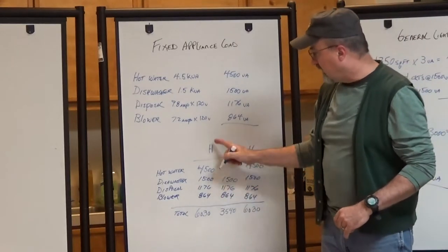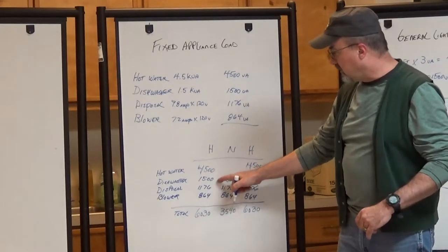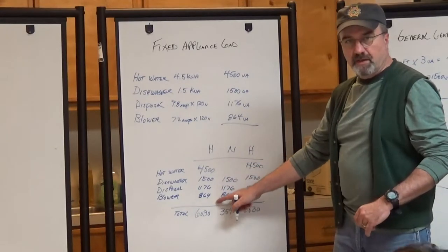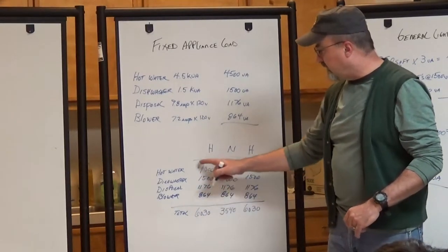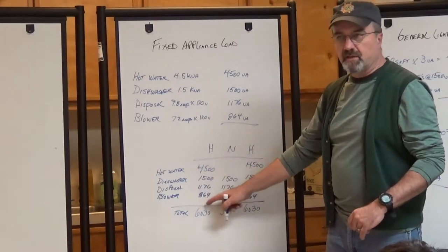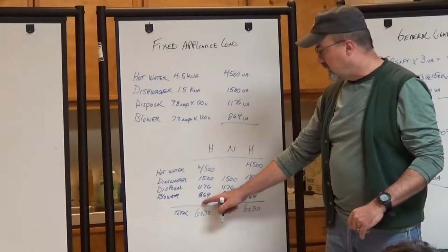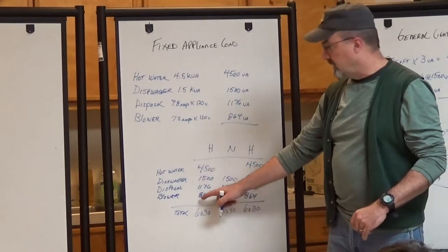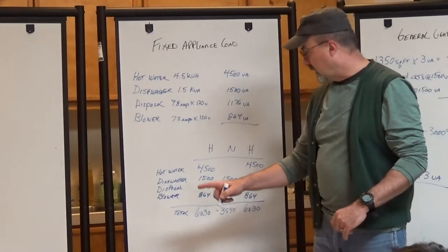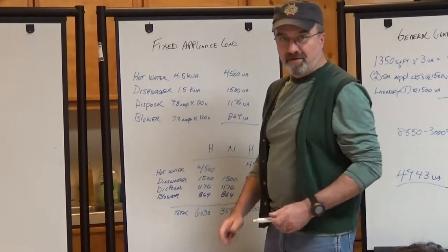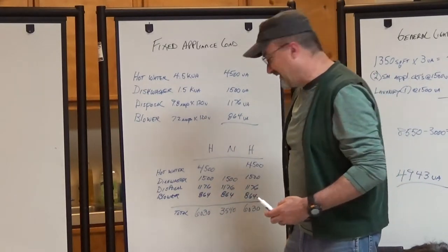So you take the hots. How many fixed appliances do we have fastened in place right here? 4. 4, right? Yeah. It looks like they already took the 75%. Yeah, we did. I didn't even add that up. I'm going to have to check the math now, okay? Sorry.